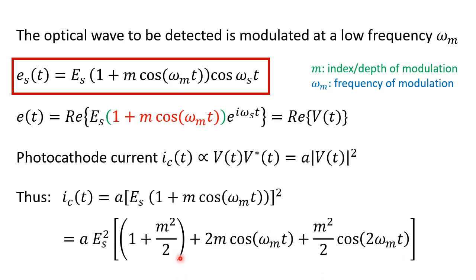So you have these separated components in the frequency space, centered around DC, centered at omega m, and also centered at twice omega m. So carefully, one can now put in band filters and pick up the signal of your choice, right? That is what one does.